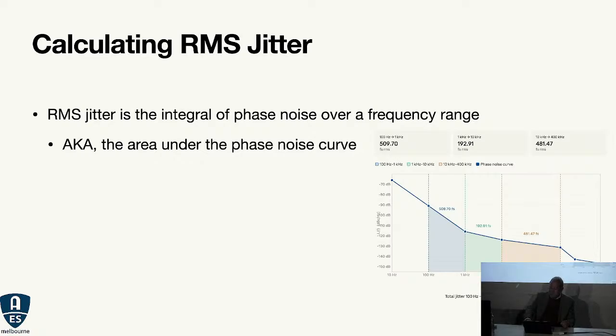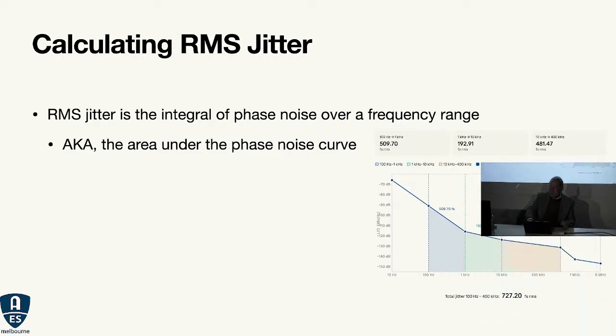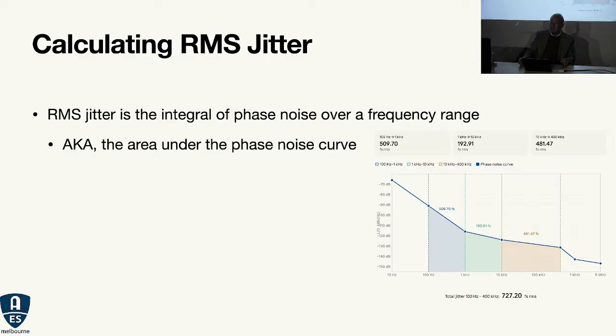So here's that oscillator that we saw much earlier on. This is off its data sheet. I've munged this a little bit because that's a 100 megahertz oscillator, and I want to know what it's like at 24.576. So I have mapped it down in frequency. This data has been translated to 24.576. And here we can see what the area is under each of these main areas.